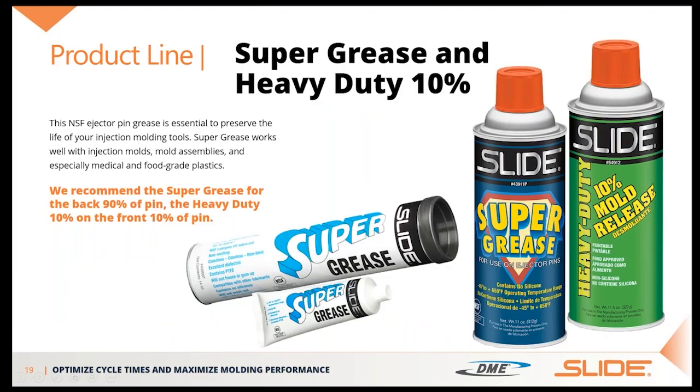All right, real quick, the super grease and heavy duty 10%. I mentioned the heavy duty earlier in the mold releases. It's called a mold release, but we also recommend it for the front 10% of your ejector pins. So for the back 90% use the super grease, and for the front 10% use the mold release heavy duty.